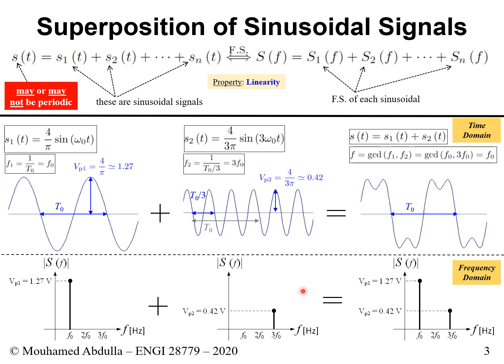So that's generally how you do it. Every time you have a value in peak voltage, you want to go all the way to dBm. You follow the steps. So find the RMS, find the P average, find dBW, and then find dBm.